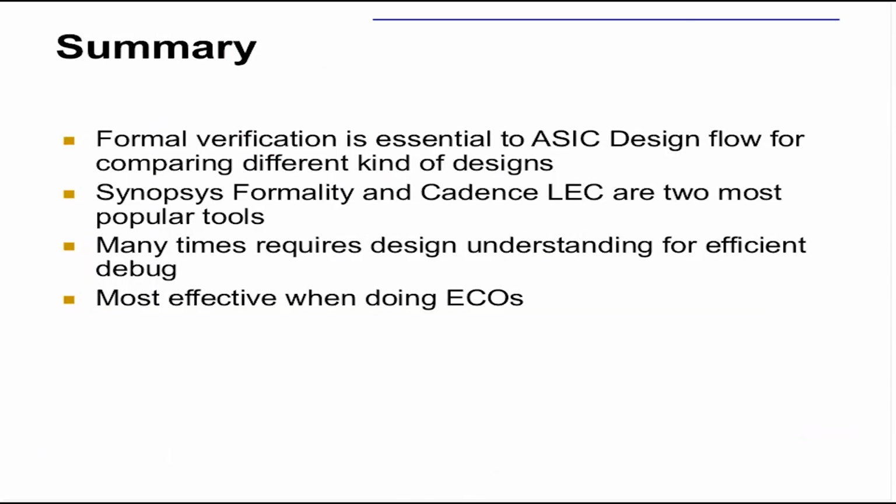So we discussed the importance of formal equivalence in the ASIC design flow. We saw the ASIC design flow and we saw that formality is very essential to make sure that any synthesis flow or any PNR flow or any RTL modification flow is not causing any functional disturbance. So formality is essential. I'm underlining the word essential.